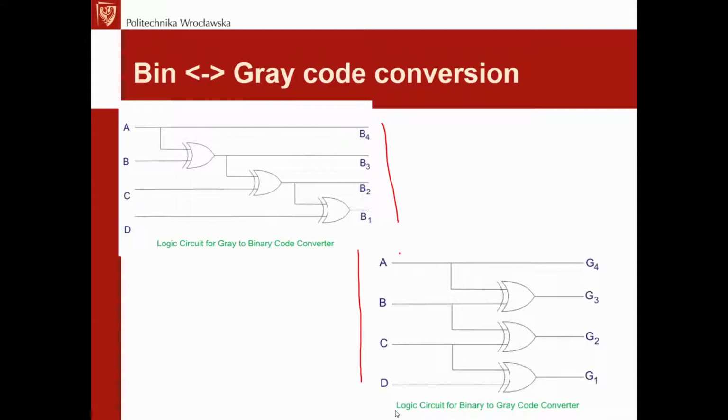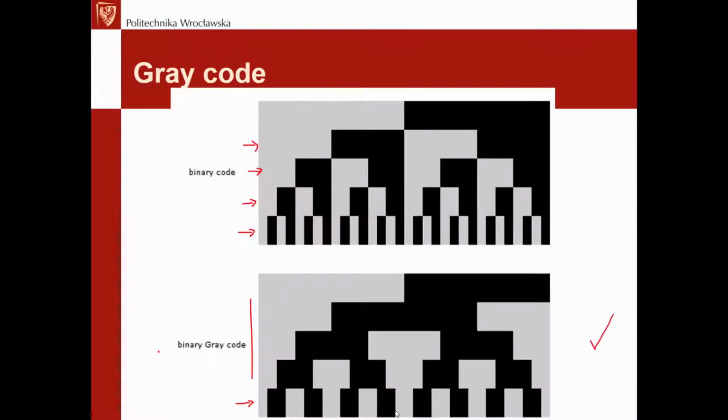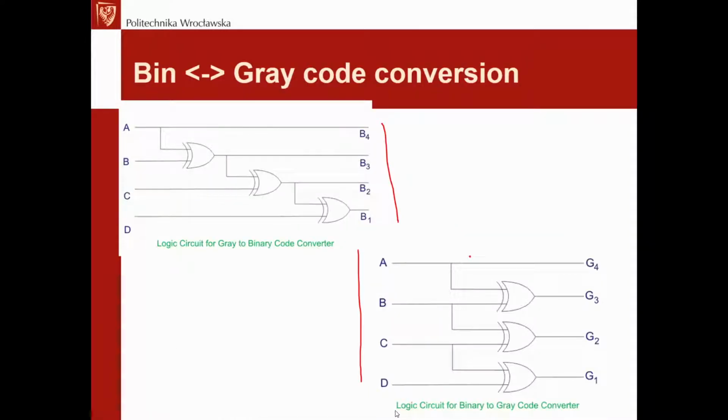So mind that we can save a lot of energy and a lot of problems in electronics thanks to this coding, because we are reducing the required output frequency from the sensor. Yet we can still interface such a gray encoded element or sensor very easily to a simple binary microcontroller, because it's enough to use 3 simple XOR gates, so exclusive OR gates.